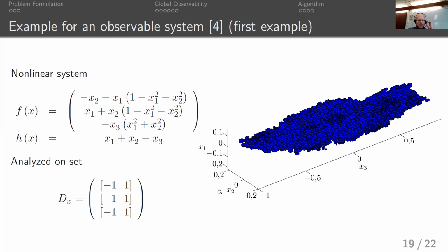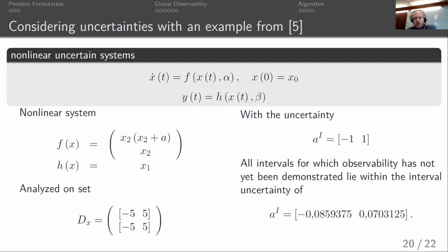Okay, I think the first question of Luc gave me something that I wanted to ask. When you're extending your state vector by a further uncertain parameter, a time constant, a new state variable, I think you're proving the observability of the parameter itself. And the other thing you did is, when you're plugging in an interval bound for your parameter alpha or a, in this case, I think you're proving observability for the union of all realizations of this parameter. I think this is slightly different.